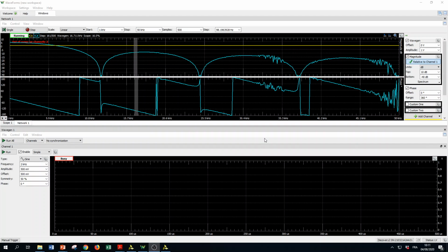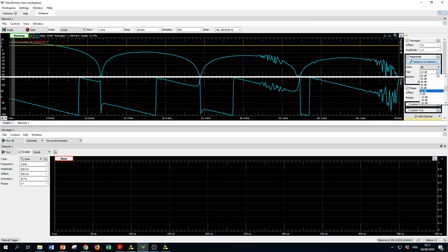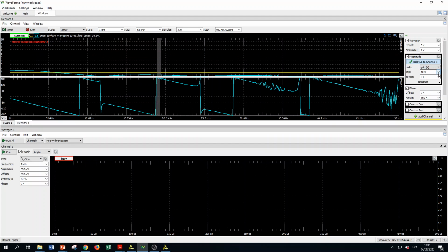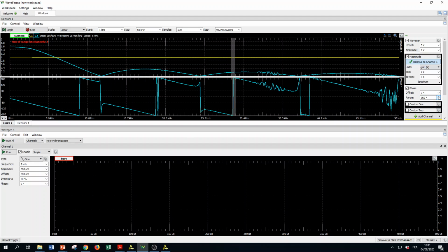Okay, so if I connect the signal correctly, you have the filter. Because it is a moving average with 8 coefficients, you have all over the bound 8 zeros. So it is 1, 2, 3, 4, and 4 others at the negative part of the spectrum. Okay, so it is good. So we can also play with that in linear if you want. So it is in linear, so maybe 2x. Okay, so it is the filter. Okay. Good luck. Thank you.